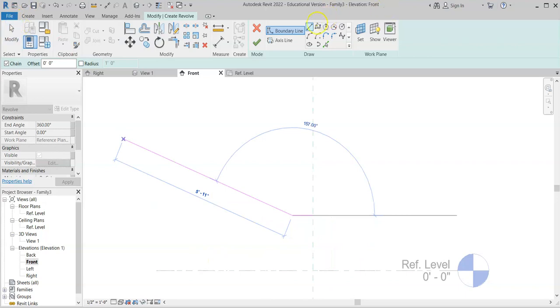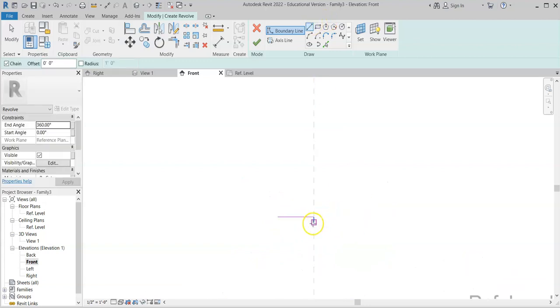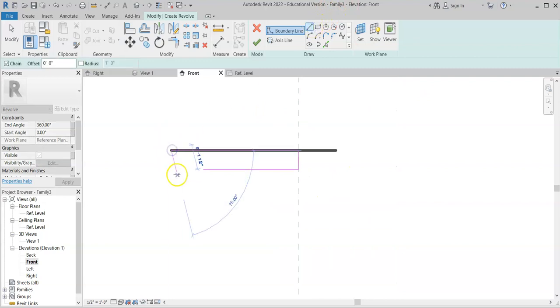The top of the table is 1 1/8 inch thick. So I'll draw that line. Give a slight beveled edge, so I'm going to draw 6 inches over. And then draw the slight bevel. Starts at 1 1/8 inch.